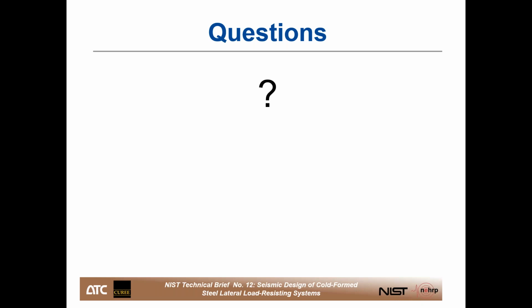What are the conditions where gypsum board can be used for shear walls? And then the person went on to say that assumed design conditions are not necessarily found on construction sites. For example, there's the potential for extreme humidity and transportation damage hazard. Yeah, so in terms of what the specific limitations are, I would say let's answer that one in the written responses, because I would want to refer specifically to S400 to make sure I don't miss something. But yeah, that's absolutely right, that gypsum board is highly sensitive to humidity, and it can be subject to damage.